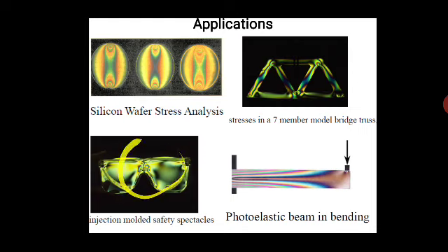So you can observe here the joints which are subjected to maximum stress. The area at this point can be varied because of the data obtained from the photoelasticity technique. So by this we can prevent the failure of such a member.